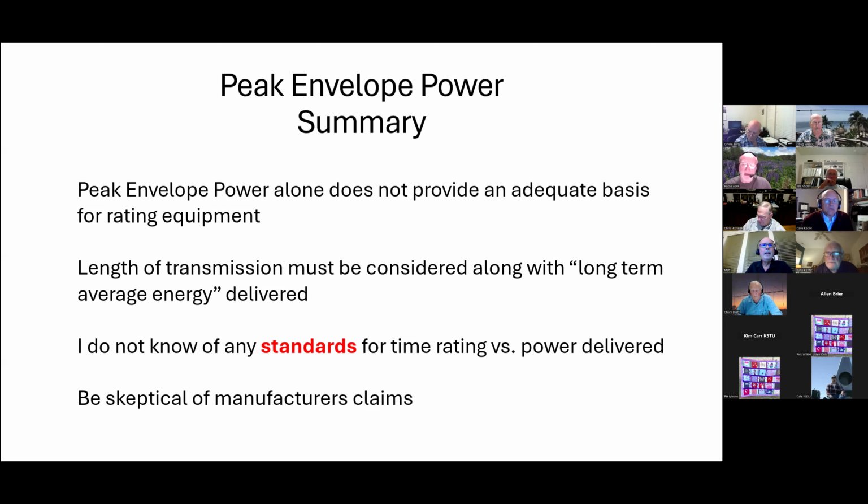Except if you had 1 kilowatt on your final amplifier and it was 100% plate modulated, your instantaneous power was 4 kilowatts. But they knew that, right? That's the way plate modulation works. So today, if you take a modern transceiver like my K3 and put it on AM, you're limited to 25 watts. That's because whenever it peaks, the peak power is 4 times that, 100 watts, and that's about what this amplifier will deliver. I found that pretty interesting.